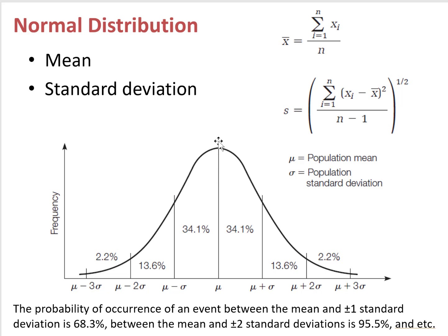For example, this is the required average compressive strength, and the specified compressive strength is somewhere here. Then, since the sample will follow the normal distribution, we will have about 90% of the samples having a higher compressive strength than the specified value.